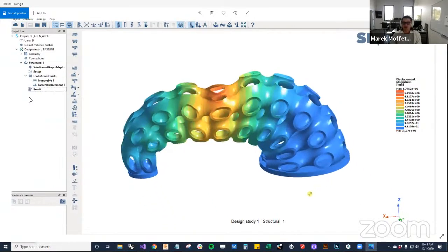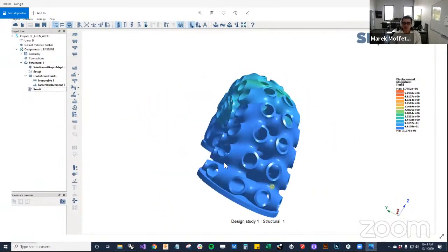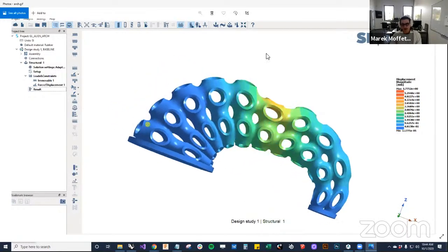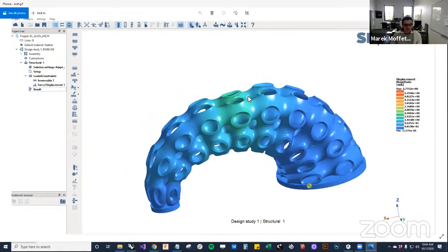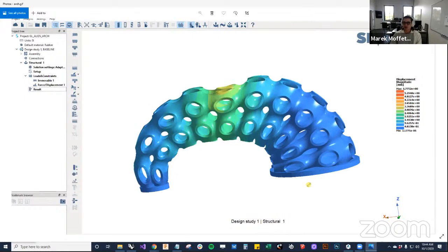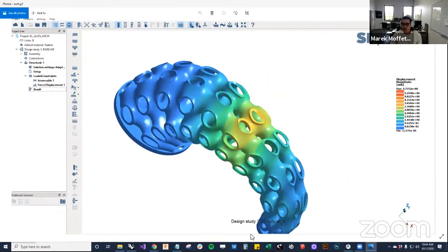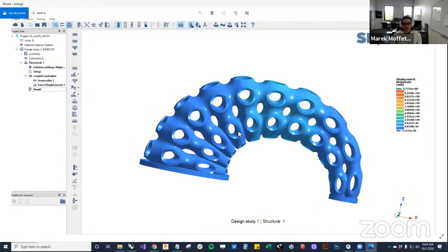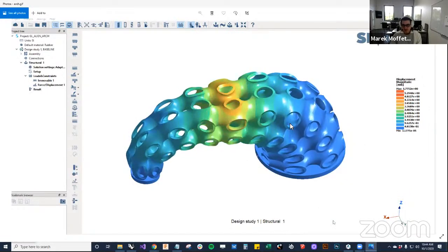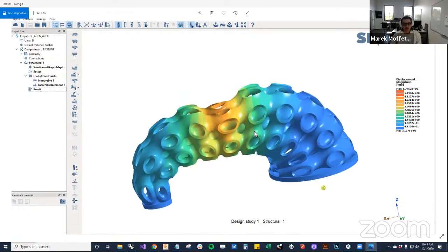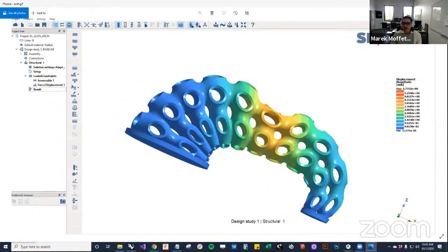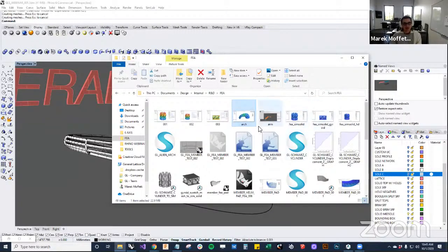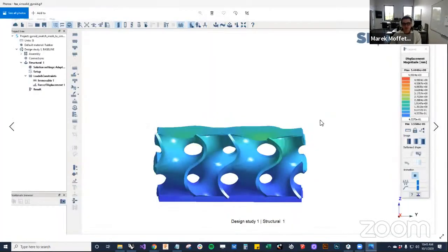I simply just imported this as a step file and constrained the 2 planar faces at the bottom, and added a pressure load on the BREP faces that I clicked. And again, the speed at which you don't have to optimize your mesh, and then don't have to do painful mesh face selection for placing your loads and constraints is truly an exciting workflow, as many know that up to 80% of FEA is actually geometry preparation, and we're really aiming to eliminate a large part of that.